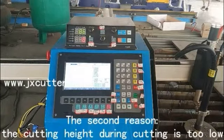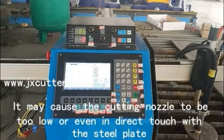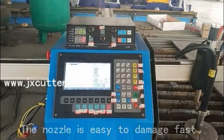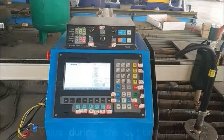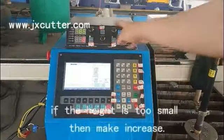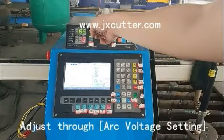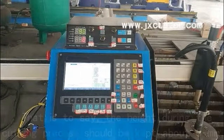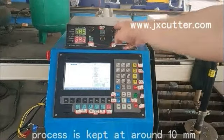The second reason is that the cutting height during cutting is too low. It may cause the cutting nozzle to be too low or even in direct touch with the steel plate. The nozzle is easy to damage. The solution is to adjust the arc voltage during the cutting process. The distance should be kept at 5 mm. If the height is too high, please reduce it, and if the height is too small, then increase it. Adjust through the arc voltage setting. That is to say, the height during the cutting process should be kept at about 5 mm. The positioning height during the arcing process is kept at around 10 mm.